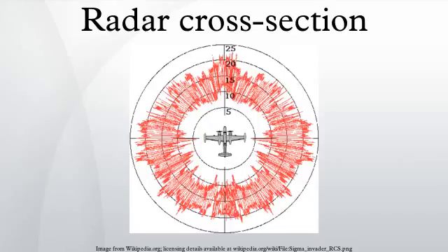The first term in the radar equation represents the power density that the radar transmitter produces at the target. This power density is intercepted by the target with radar cross-section sigma, which has units of area. Thus, the product is the dimensions of power, and represents a hypothetical total power intercepted by the radar target.